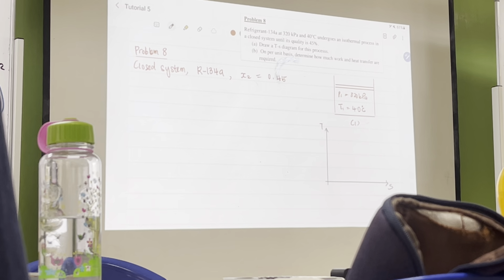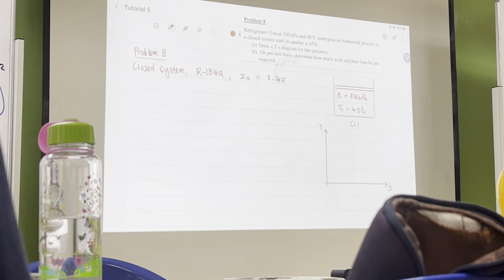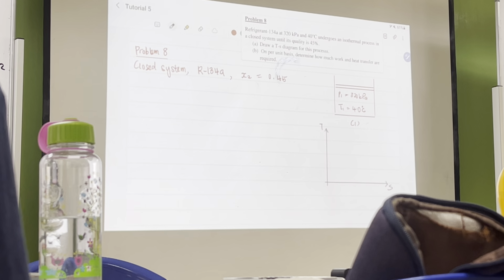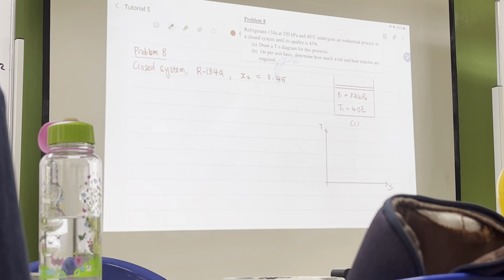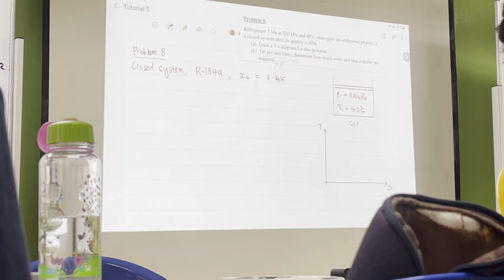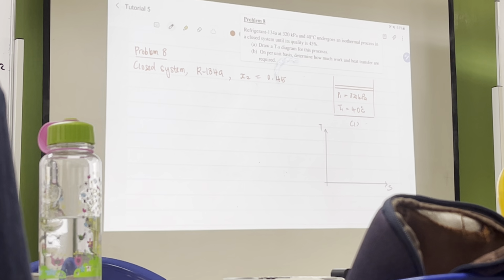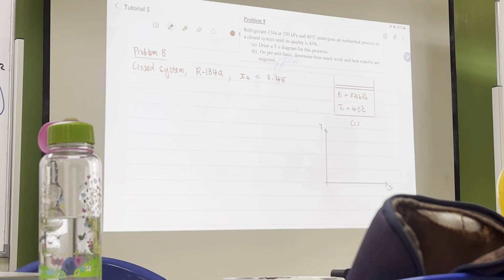Both of them, see which one you can understand better. Actually, that table alone cannot give you the answer. If you have 0.32 megapascal there, the closest one is... I don't need any value here. This one, what state is this? Superheated. Okay, so the initial state is a superheated vapor state for R134a.